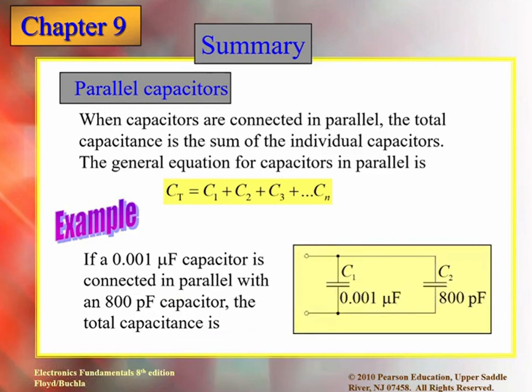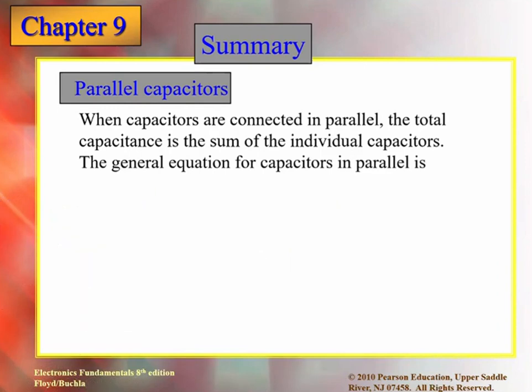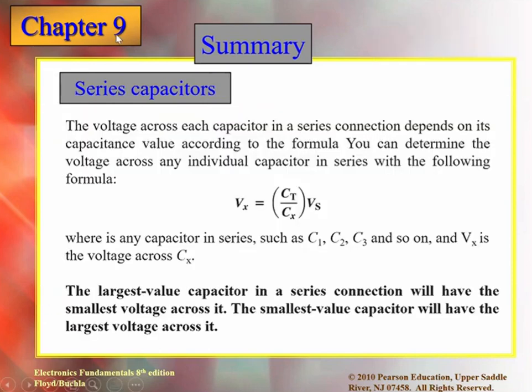So this is the formula. And by the way, do you remember the voltage divider, current divider formula for the resistance, girls? Ix equals Rx over R total, times IT. Do you remember the general formula for the current when currents are there in a parallel circuit? It is going to be the same, basically. So this is the current divider type of formula.